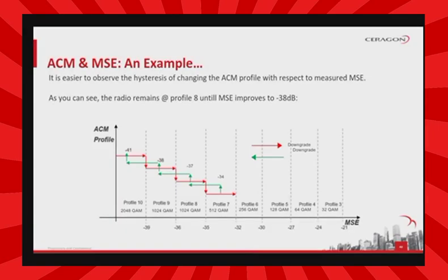An ACM radio script is constructed of a set of profiles. Each profile is defined by a modulation order, QAM, and coding rate, and defines the profile's capacity in bits per second. When an ACM script is activated, the system automatically chooses which profile to use according to the channel fading conditions. The ACM-TX profile can be different from the ACM-RX profile.